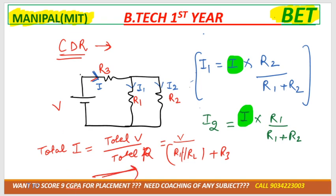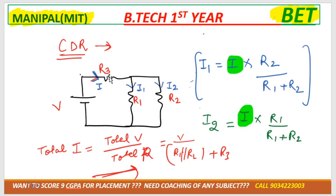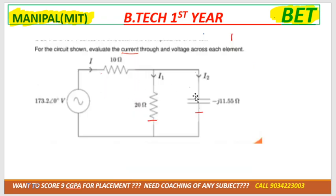Okay, so see, this is a question from your question paper only, BT Manipal. In this circuit it looks the same, just as I drew the resistor-based circuit. In this they said evaluate the current and voltage across each element. Basically they are asking the value for I2, the value for I1, and the value for I. So it's better to use the current division rule.